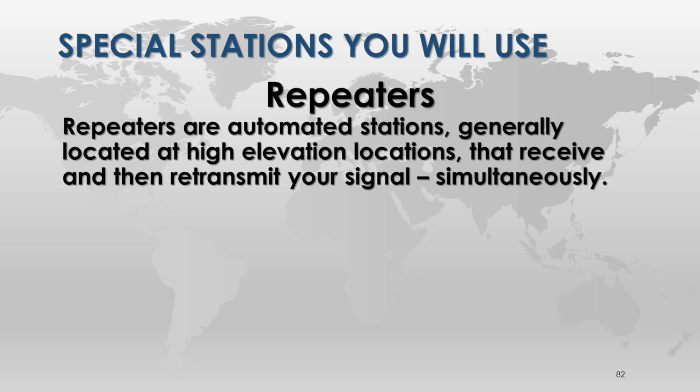That's the output of the repeater, so you're listening to that. You just need to know if it's positive or negative, unless it's a non-standard shift, which can happen. And then you need to know the tone, which we'll cover later. A lot of modern radios will automatically put in positive or negative based on the conventions that are generally used. But you could be on a repeater that's opposite to the general convention and have to manually input the offset.